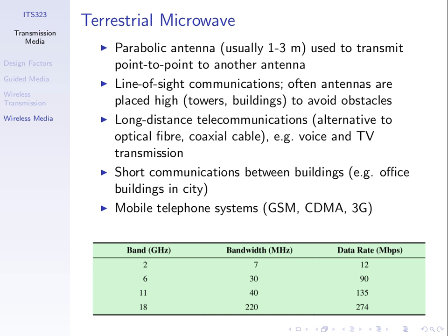A mobile phone tower will normally provide coverage with a radius of several kilometres. The link between our two campuses is about 12 or 15 kilometres, maybe 30 kilometres for some wireless point-to-point links, using frequency bands from about 2 gigahertz up to 10, 20 gigahertz. So one example of wireless media uses either point-to-point links over a long distance, or in some cases point-to-multipoint, for example TV distribution and mobile phone systems.